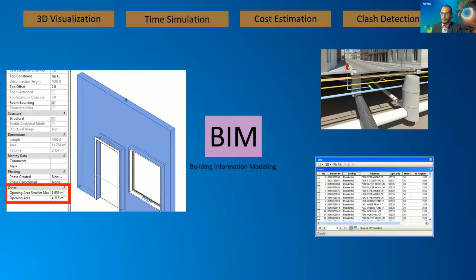Of course, without BIM, you may face problems like that. So maybe a duct and a beam in a building that are supposed to be clashed in the model, but it cannot be like that in the real world. So you have to stop the project and send an RFI or a request for information and wait for a couple of days to receive the final decision.